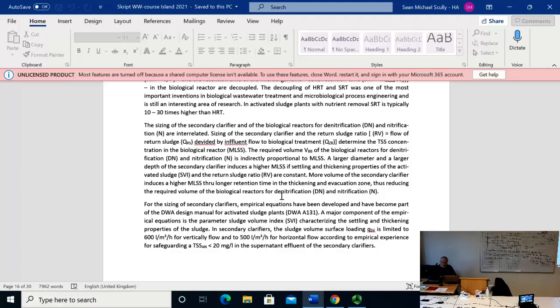We require a maximum food to mass ratio, and thus you have a minimum mass of microorganisms you need in order to eat all that food. Like if you have a mouse eating a kilogram of cheese, maximum not more than a kilogram a day, and you want 5 kilograms of cheese eaten a day, then you need 5 mice to eat it. And when the mouse only eats half a kilo, then you need 10 mice. This is what I'm talking about.